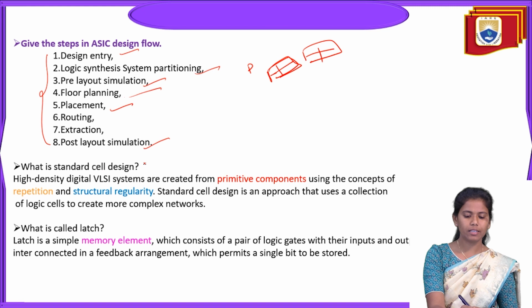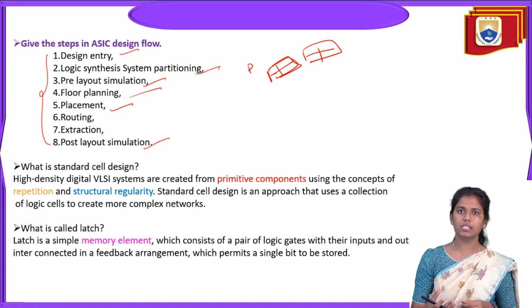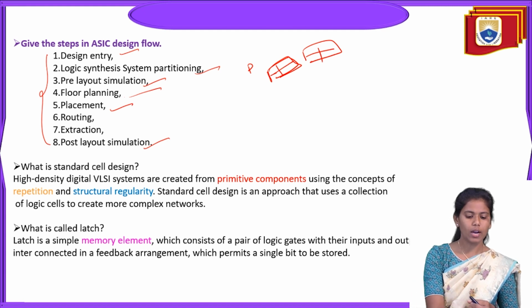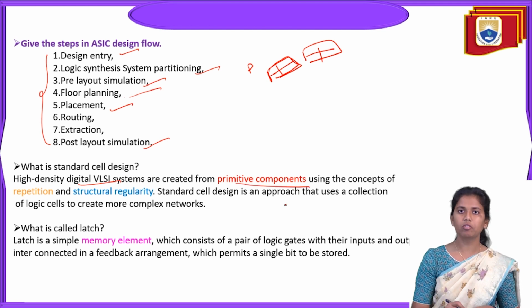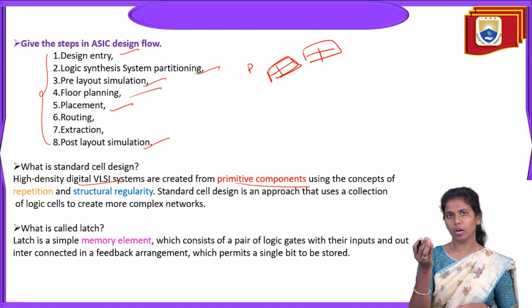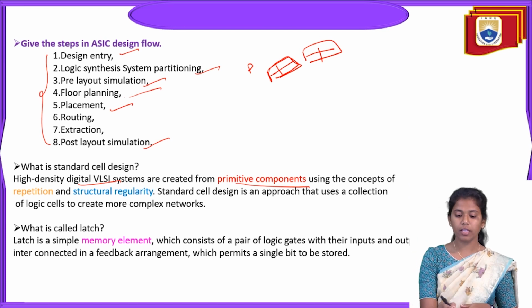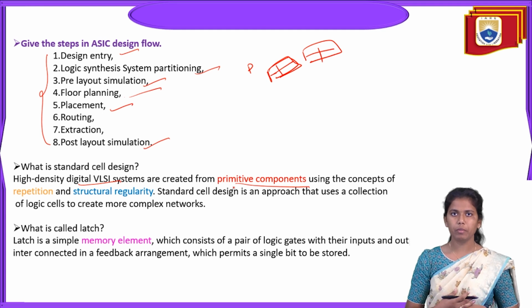Then what is standard cell design? We basically know the cell, but how will we design a particular standard cell? High level digital VLSI systems are created from primitive components. So we know that in order to design a small circuit, we take the primitive components. The basic components can be considered from the Verilog, right?